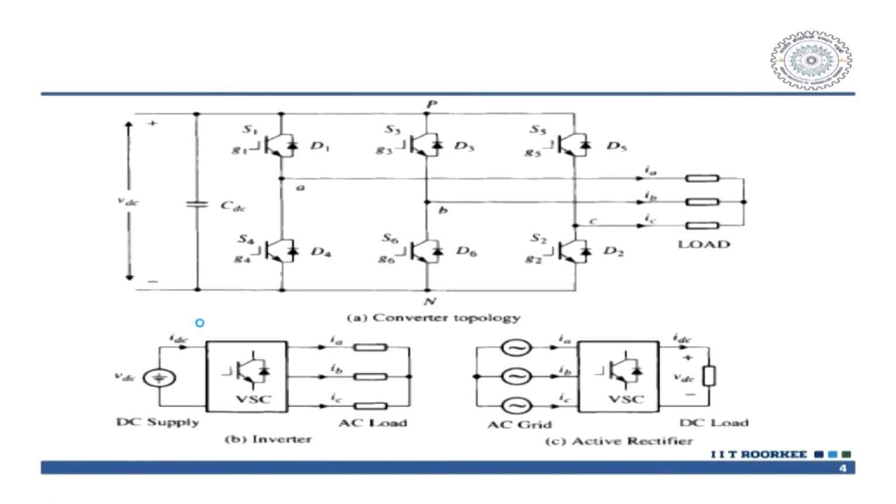So, if we talk about the distribution system, we may have the simplest system, that is the 2 level inverter, and then you may have a DC source here that may be a solar, and you are feeding this load. So, it is not a grid connected entity. There it is quite easy, because then you can choose a reference and force that current to track that reference. And generally, once power flows from the DC side to the AC side, we say it is inverter operation, that is what your household inverters are.